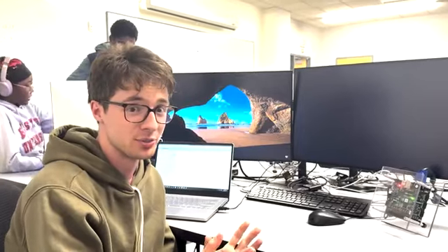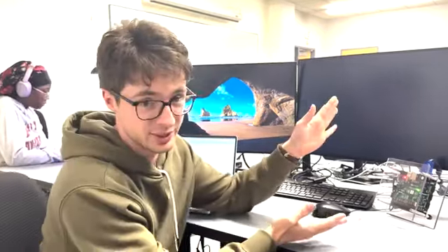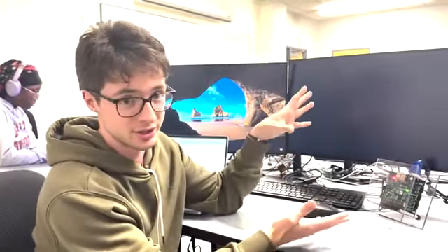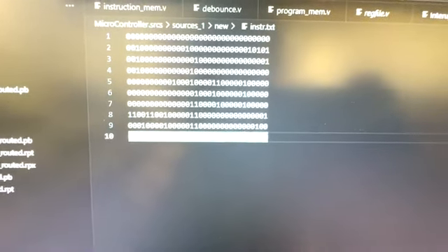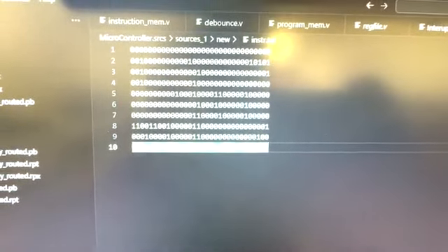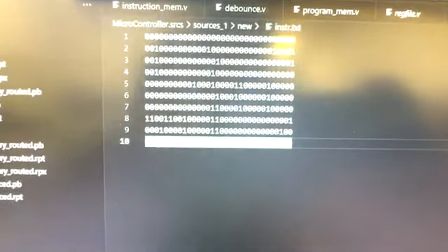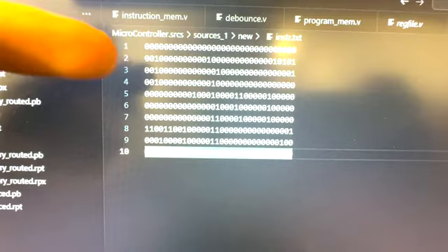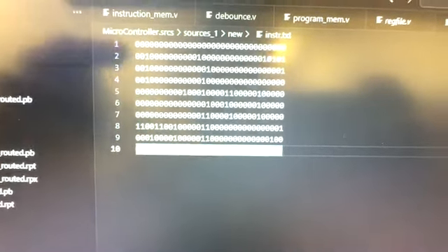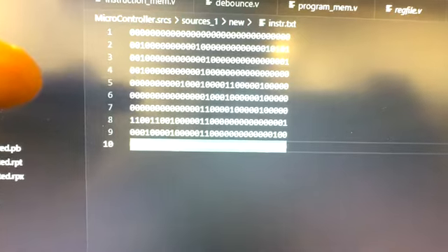All right, so to prove that our computer is reprogrammable, we uploaded a different set of firmware, and this one is the Fibonacci sequence. This is the code for the Fibonacci sequence. What it does is it has a blank instruction to make sure that the CPU is completely ready for actually starting the code. And then we are loading variables into first what number we want to stop at, and then the two starting numbers, so 0 and 1.